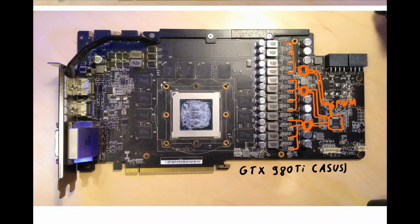Because it does improve your current capability, your efficiency, and also your voltage regulation quality. So having doublers is not bad. It's just that it would be inaccurate to say you have, in this case, a 12 phase, because it is actually a double 6. So I would say it is a 6x2 phase and not a 12.